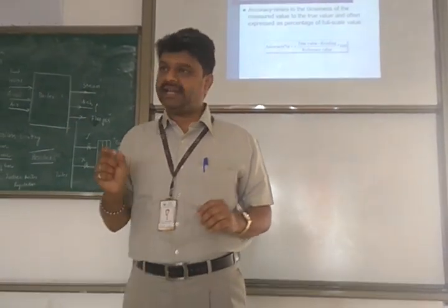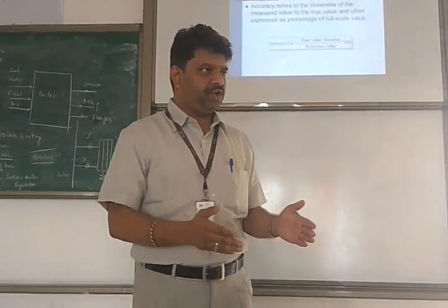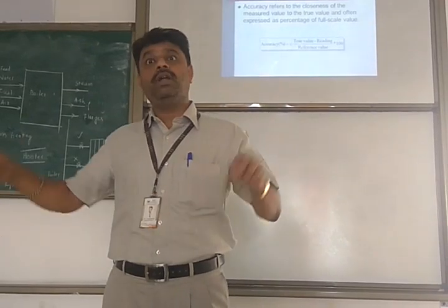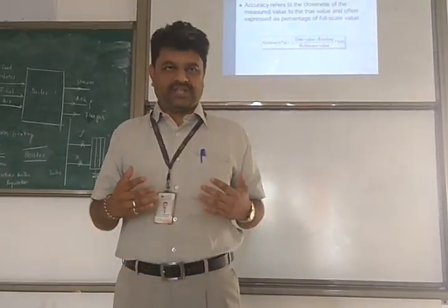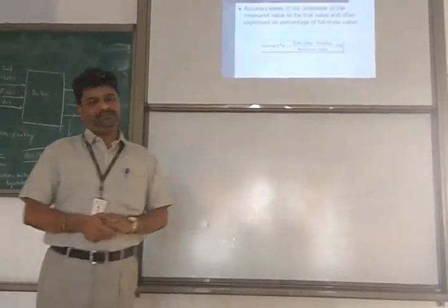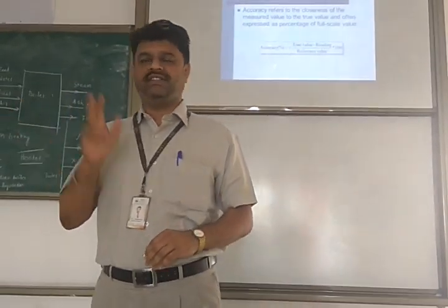Technically speaking, both are correct. Sir, I have computed accuracy using true value. Sir, I have computed accuracy using full scale deflection. Both are technically correct. So as a manufacturer, I prefer to use FSD because that gives a smaller number. I have two choices. One is true value, the other one is full scale deflection.